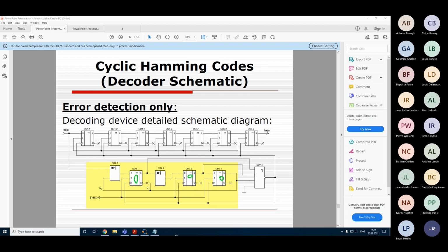And accordingly, how do we know that it's okay? Well, we use a simple OR operation. Please don't mind this NOT inversion, it's incorrect. It's just a simple OR operation without inversion. Basically, if any of these contents is 1, for example like this, then OR will produce 1 at the output, which is the signal of the error.